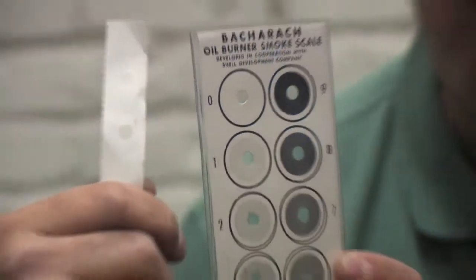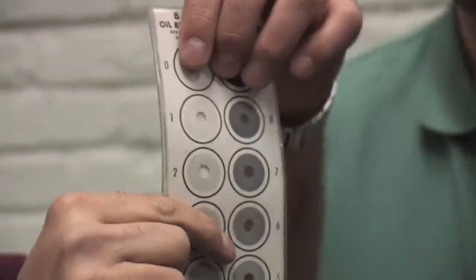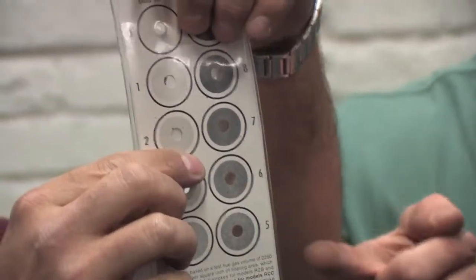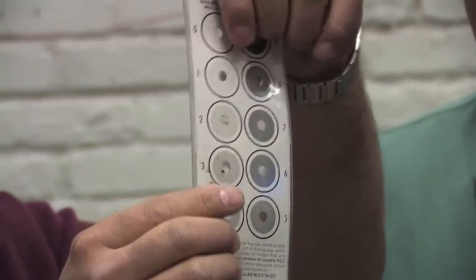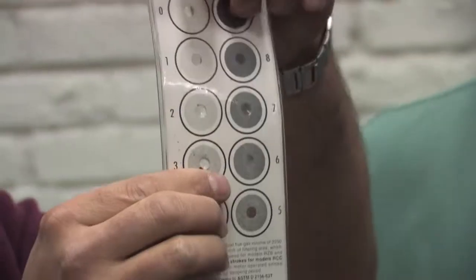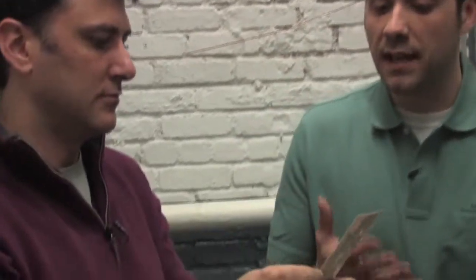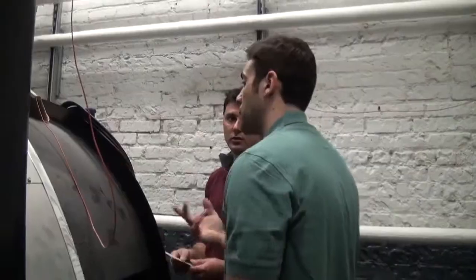So what we have inside the smoke tester is we have a little scale that's provided with it. And we can match it up and we can get a number. And that number will correspond to how dirty the flue gases are, how much carbon is inside them. We want to see something that's less than 1. So in this case, we match it up. We're probably right about 3. I would say 2.5, 3. So that means that it's a little bit on the dirty side. So we're not getting clean combustion. So this is done before we do the analyzer.